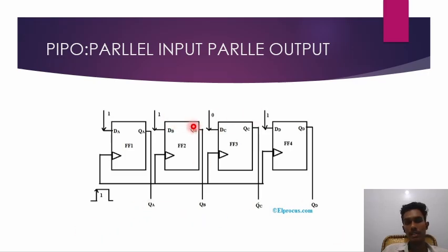But in a series register, we have to wait up to n minus 1 clock cycles. Here, we do not need to wait up to n minus 1 cycles. As we give the input, we get our output. This is parallel input and parallel output. Let us know the applications, meaning the benefits, of this parallel input parallel output connection, the parallel input shift register.